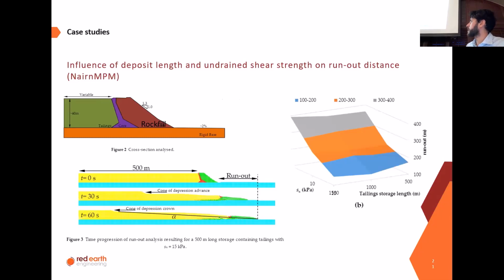Now I'm going to move into a number of case studies, some of which I have authored, and some of them are being done by others. So this geometry is actually the geometry that you see in Kenya. The tailings in Kenya weren't actually liquefiable. Sorry, no, this is not Kenya, this is Mount Polley, my apologies. So the tailings in Mount Polley weren't actually liquefiable, and the reason they flowed was because they were eroded with the ponded water on top of them.